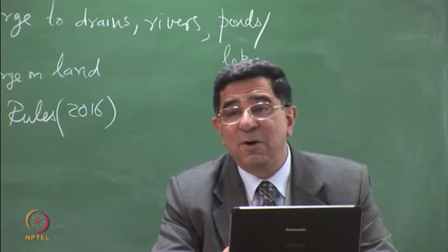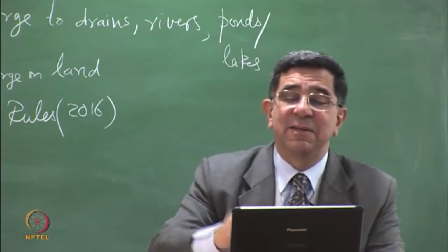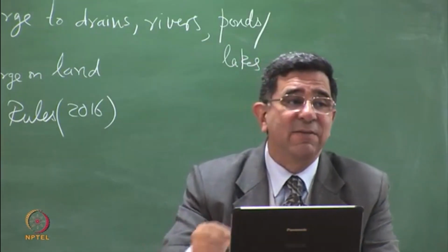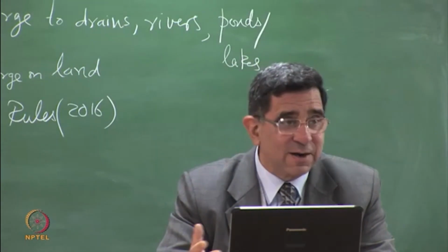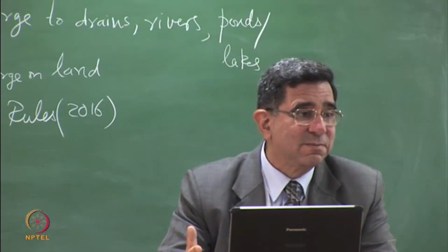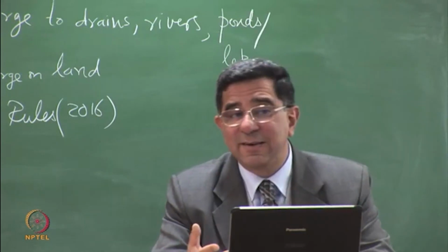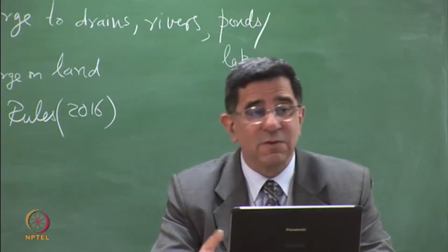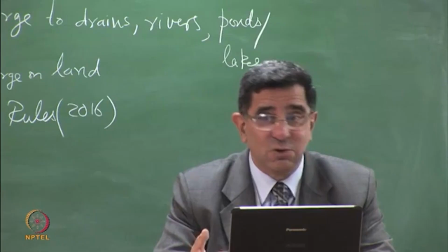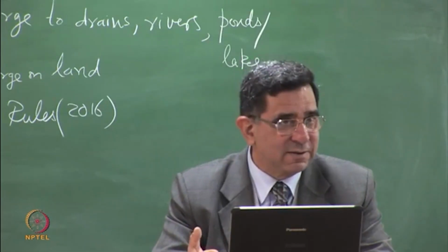I can accelerate the process in the lab, and I can estimate the number of cycles which may come in a lifetime of 15 or 20 years, and I can do that test in 6 months. So this could be the durability test. These are accelerated tests. So when we study durability of geomembranes, which you will do in geosynthetics, there will be accelerated tests.